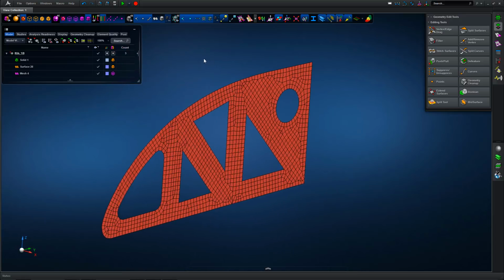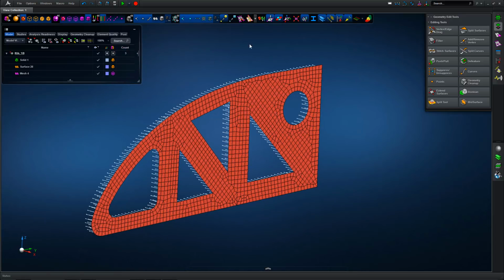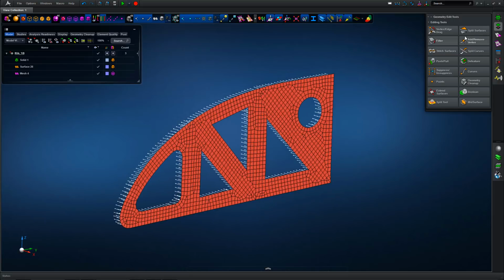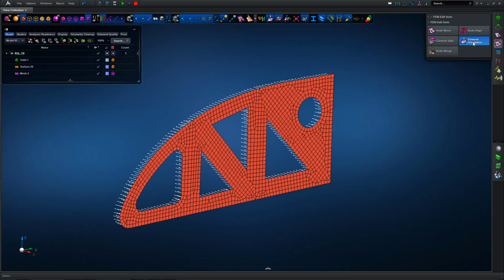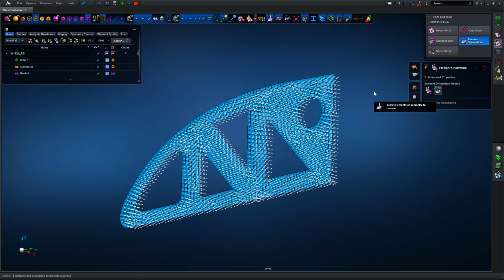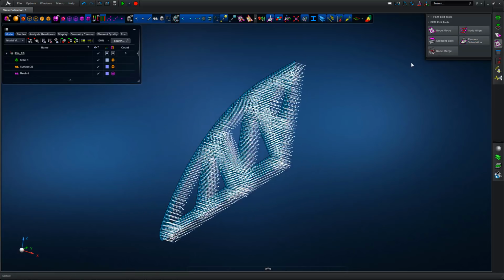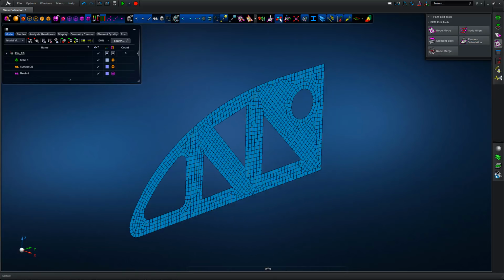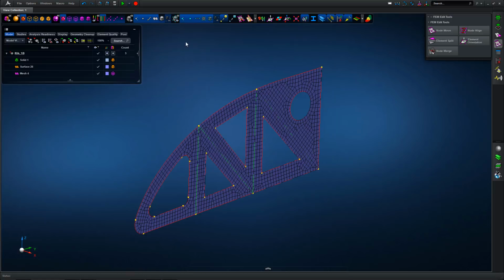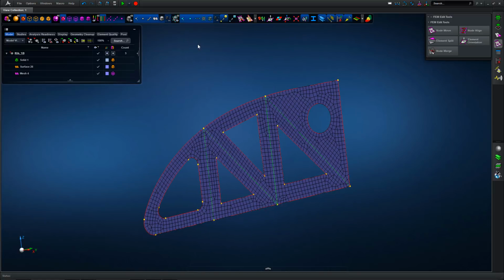Checking the surface normals. First of all, checking for surface consistency. We can see all the normals are pointing in one particular direction. We actually want the normals to point in a different direction based on the output quantities that will be developed for the model. So a simple check and then update to give us the orientation definition that we want.